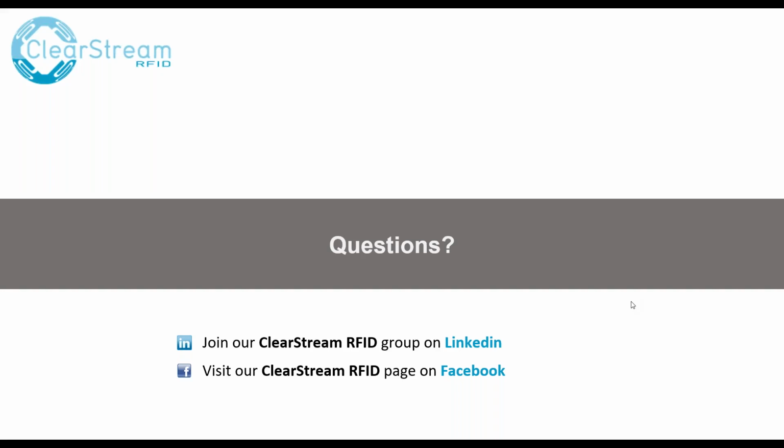Some of these are getting cut off, so I apologize. So question, when you say station, as in station 1, station 2, et cetera, can this be given a specific name, as in single, double, or home run? Yeah, so for workstation 1, I just gave it as the antenna name. That comes over with the tag data as it's reported to the endpoint as the antenna that read that tag event. So you can name each of those antennas differently, and they'll come over with that data as you need them. You can really name it whatever you'd like, and you can get a zone or a workstation that a particular item was scanned on for that tag event.